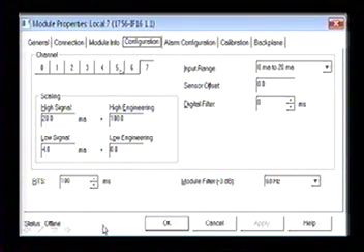Okay, so here we actually went through this already, and I'm just kind of recapping. We have configuration. We have a 1756 IF16 card. We've configured channel 7, 20 milliamps equals 100, and 4 milliamps equals 0, so we've said its engineering units are 100%. Could be a 100-meter tank, right? Doesn't really matter. Input range is 0 to 20 milliamps, and we've got a little delay in there, and it's got a module filter of minus 3 dB.